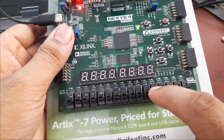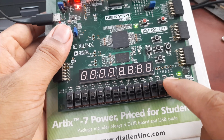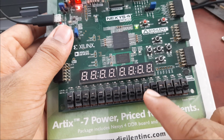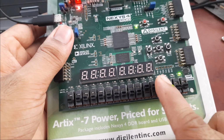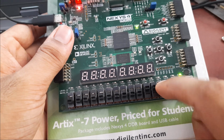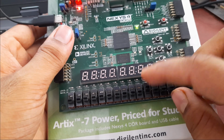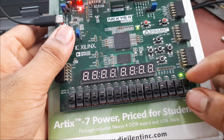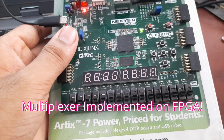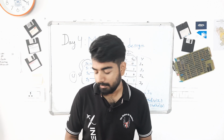Similarly 1 0 will select this line and nothing else, and 1 1 will select the I3 line and connect I3 directly to Y. So this is the application of a multiplexer. As you can see, none of the other ones are responsive. So you saw the working of a 4x1 multiplexer on the FPGA.